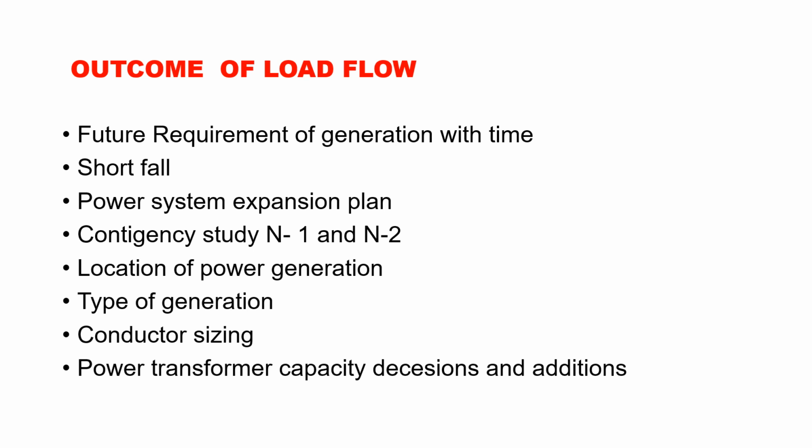And in the end, you may find that some generator is overloaded, then you will have to suggest some additional capacity, or another power plant, or some lines. You have to give some proposal so that nothing is overloaded. So from the load flow study you have to ensure that the system runs properly and all the parameters are within the limits: frequency, voltage, bus angle, active power, reactive power, loading of the line, losses, everything is within the limits.